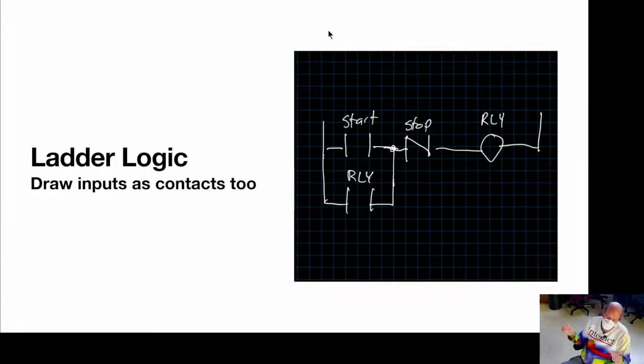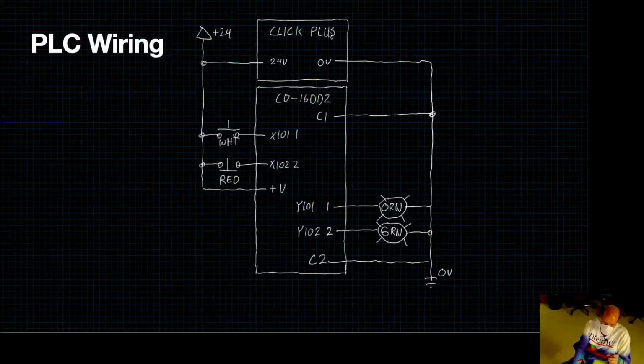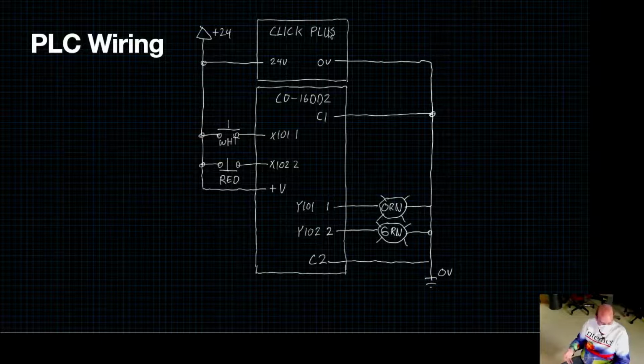As we'll see later, in your PLC, you can have a virtual component that'll do a time delay or something else that used to be a physical box that you plugged in. You'll still have physical boxes for thermal overloads or sensors and so on, but having your schematic become simplified in this way, and so much more flexible. You can have a time limit for how much the on time is, or calendar or data logging, and your electrical schematic for your control panel remains the same. So that's why PLCs are used in industry.